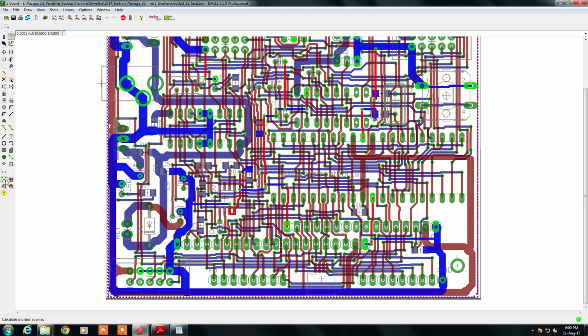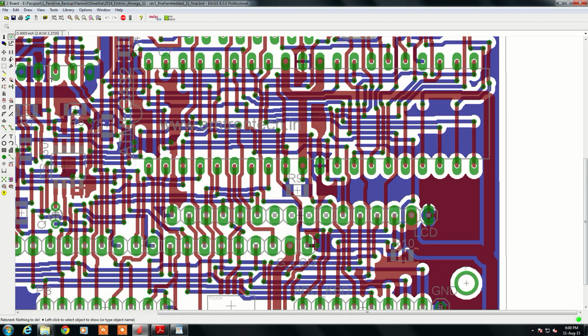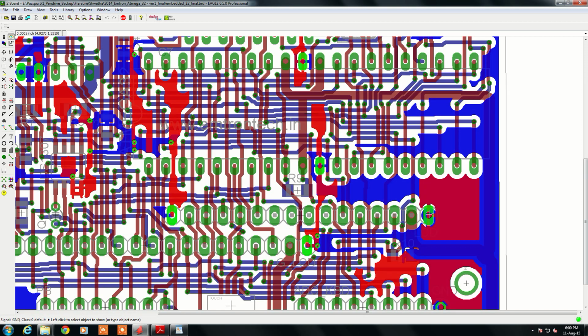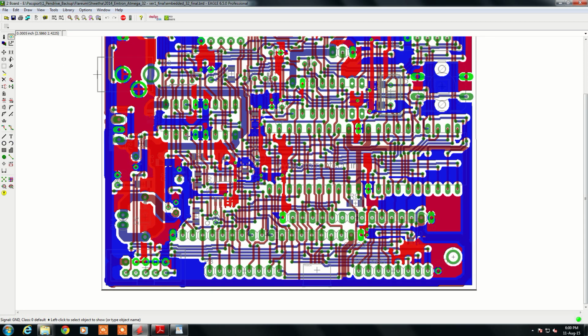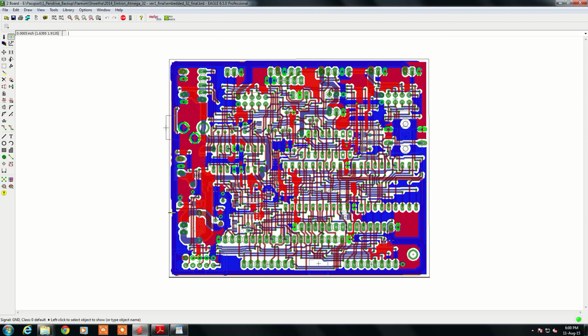So if I use this ratsnest after drawing the polygon, now you can see my entire remaining space will be filled with the ground plane. So this is now my ground. If I highlight this now, this entire area is filled with the ground wherever the space is left, which is a copper material. So this, in short, is a perfect PCB design, so that it's not only just working, but it should be reliably working.